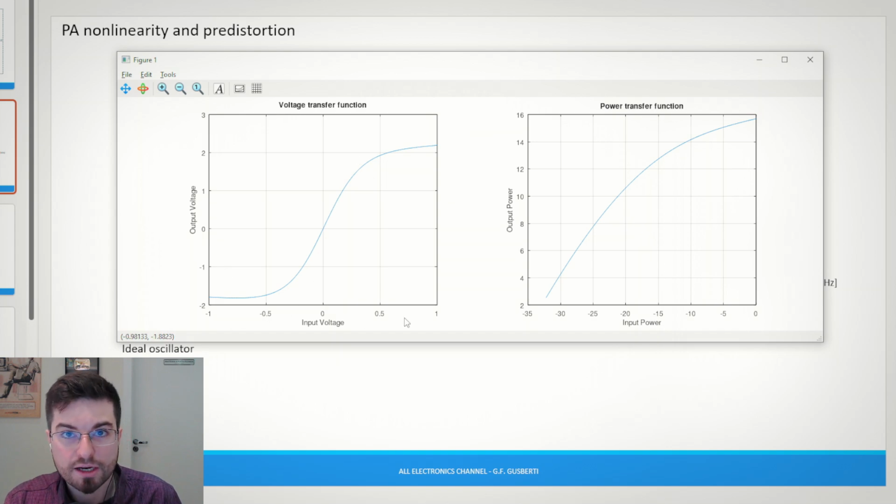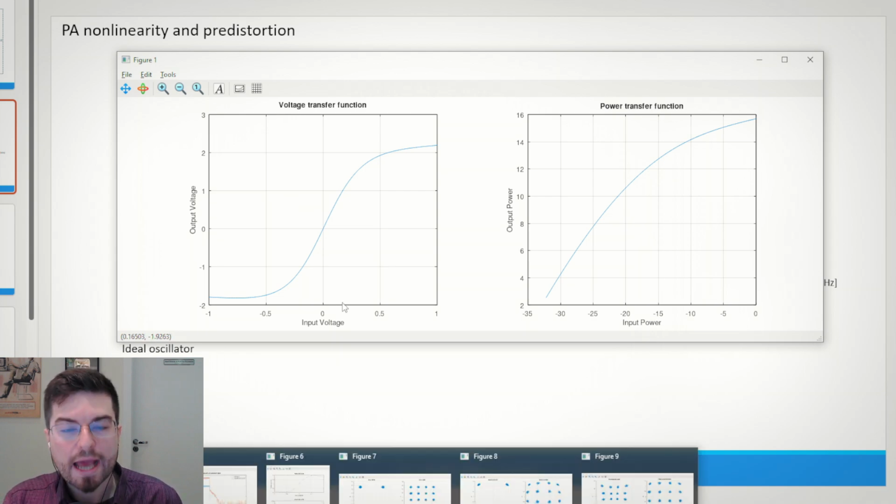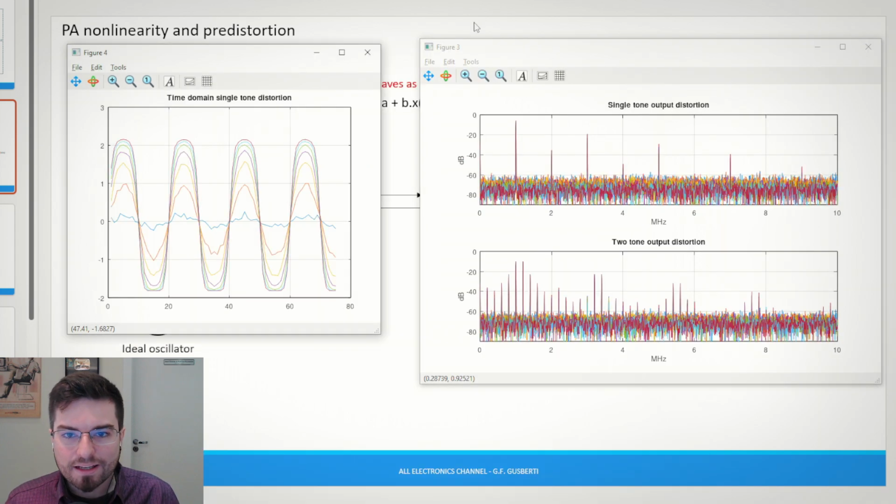the voltage excitation. So if we excite the amplifier with a very low amplitude signal, we will be working in the small signal regime here in the middle of the transfer function, and the amplifier will behave much like a linear system, amplifying the signal without generating new signal components, new spectrum. And we can see it here on the simulation. Take a look at these guys.